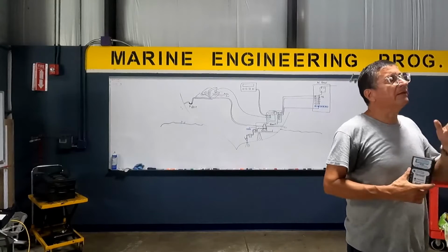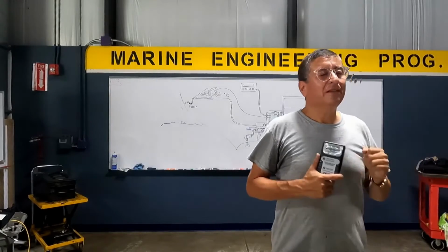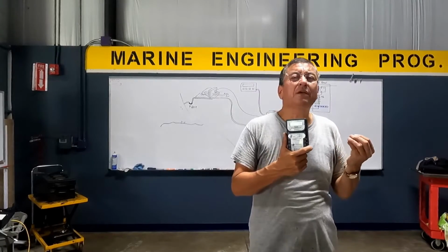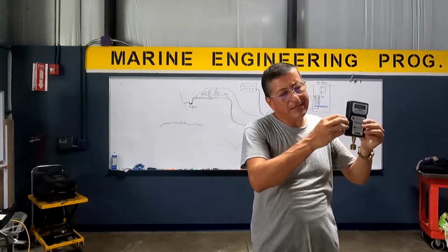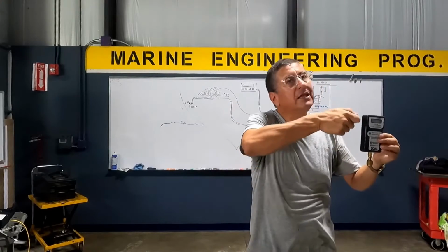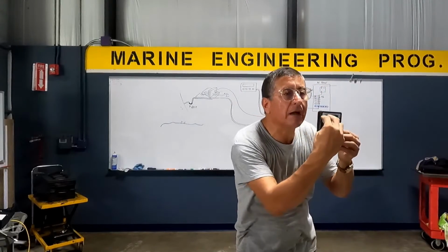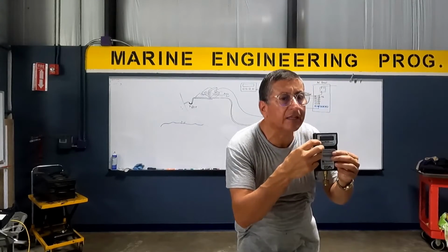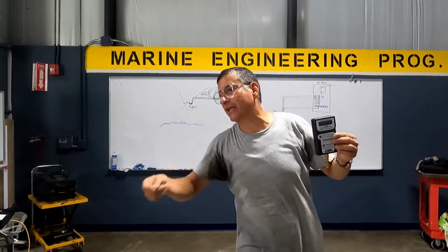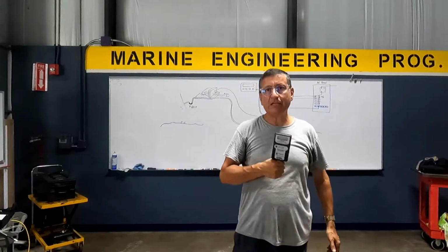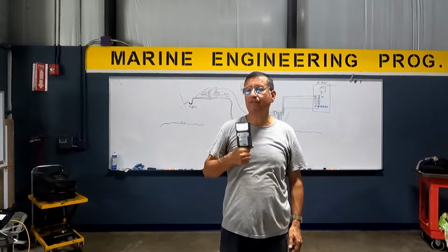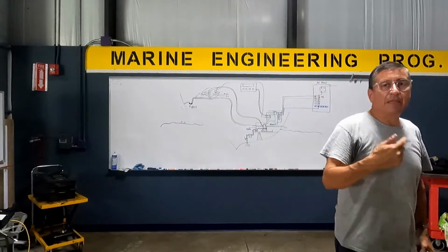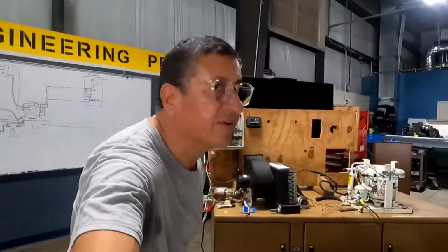My friend, I recommend in this class, check the videos, because I spent a lot of time doing the videos with too much detail. I connect this, and I wait until the vacuum is complete. I show in the camera when the number decreases until 500. I disconnect, and after that I connect the recovery tank and charge the system. Check the videos. I appreciate that you check the videos. It's good for you.